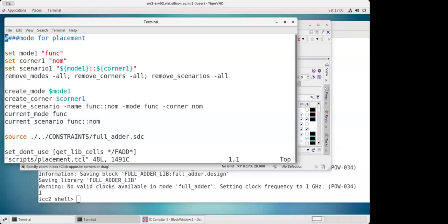The foundry is also not going to tell you what the variation is. They will say there can be an impurity, there can be a variation. That is known as the process variation. Voltage: in a wire, if the current flows, the voltage will drop. That means maybe one inverter is on 5 volts, another on 4.8 volts. There is a variation. Similarly, temperature I just discussed with you. So there are different combinations of process, voltage and temperature, and those combinations are known as the corners, PVT corners. So here we will tell the tool, okay, I want to do the analysis on this particular corner.